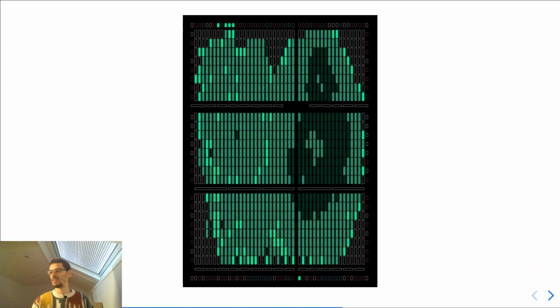And yeah, this is a RISC-V core that was synthesized using my open source tools. Because my tools are not complete yet, it's not using all the resources that it would normally use. So also the RAM is just lookup tables at this moment. So it almost fills the whole FPGA, but it works.